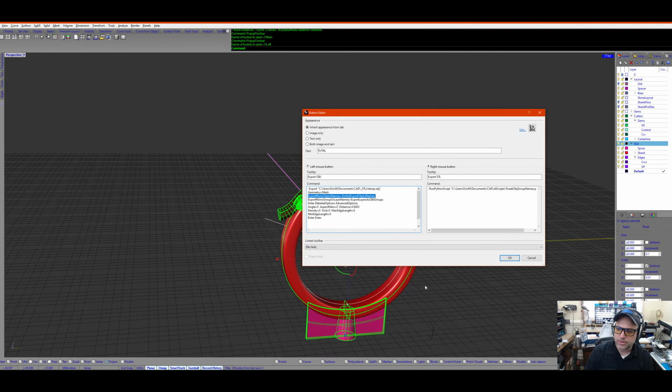Object names in Rhino are usually useless. They're auto-generated, so they don't give you anything. Instead, OBJ files let you have names on things. So I'm going to say the group or the layer name, export objects, export layers as groups. So each of my Rhino layers will turn into groups, which act like layers in an OBJ file, but they call them groups. So basically we're going from layer to layer.